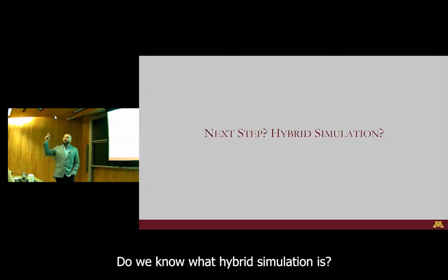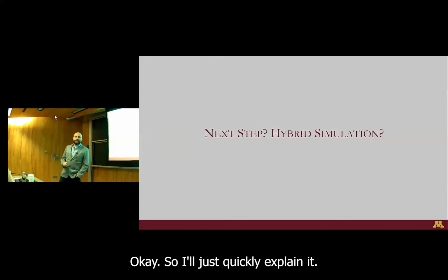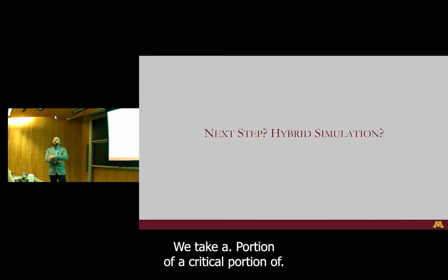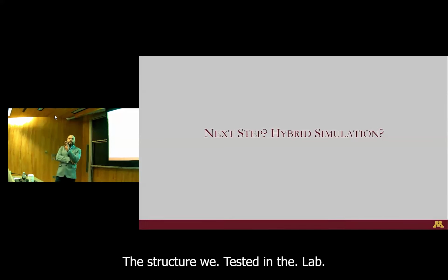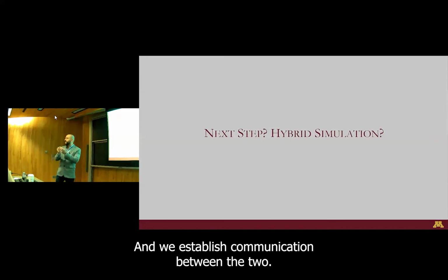Do we know what hybrid simulation is? Show of hands if you're familiar with it. Okay, so I'll just quickly explain it. So in hybrid simulation, we take a critical portion of the structure, we test it in the lab, and then the rest of the structure is modeled numerically in a numerical model, and we establish communication between the two.